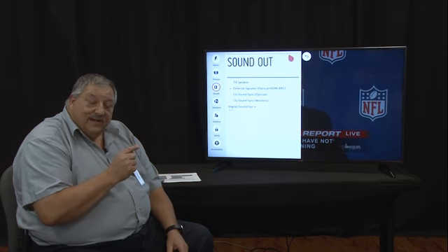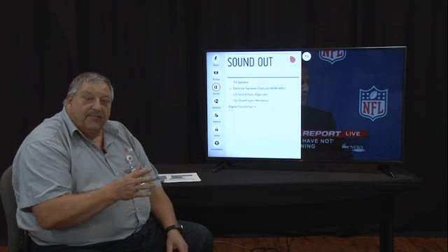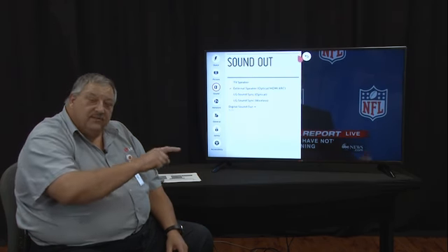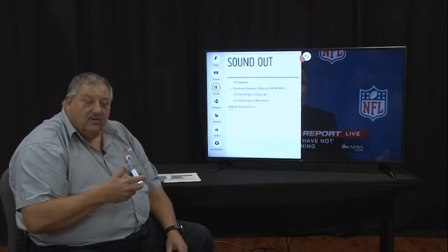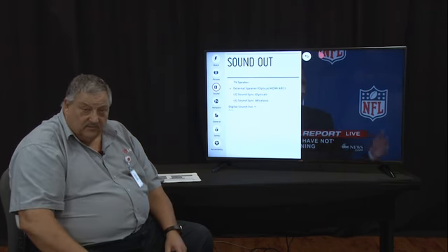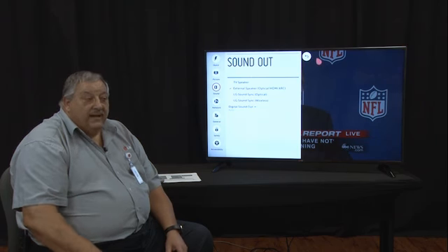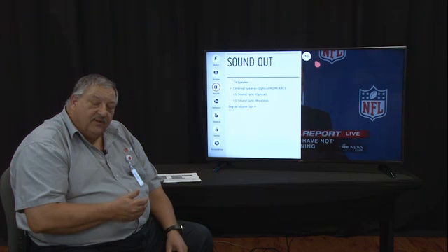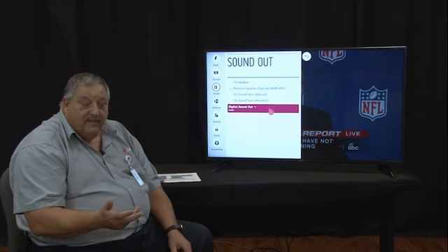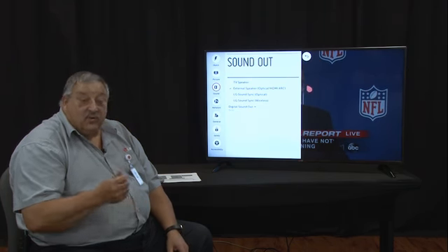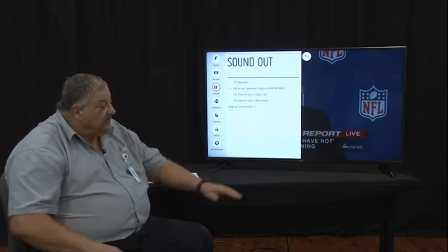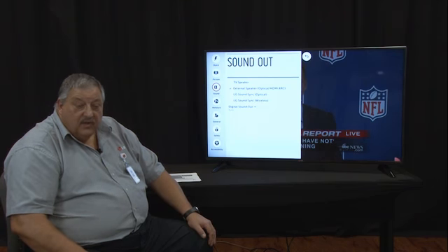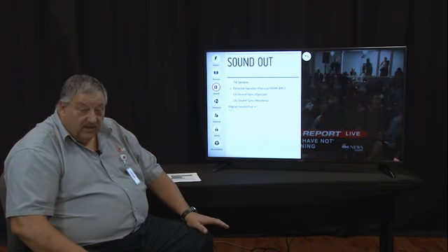Well, the Easy Adjust menu tells it about the audio. If it's set for PCM, it tells the device to send PCM audio at all times if possible. If possible. And if PCM is available, then coming out of the optical audio output will be stereo PCM. Now, usually that's what most customers want who use sound bars as their inexpensive surround system. Most sound bars will take PCM audio.